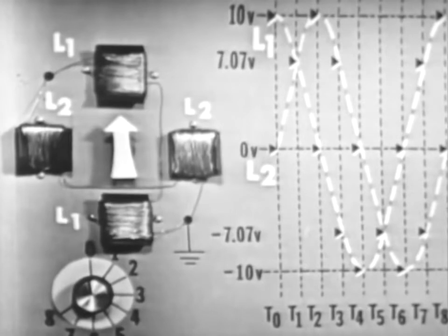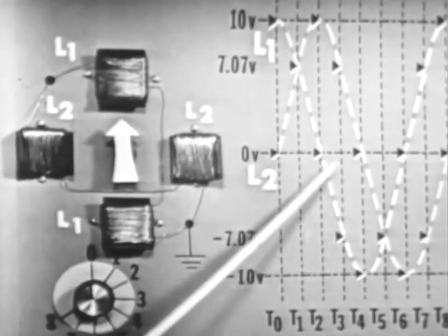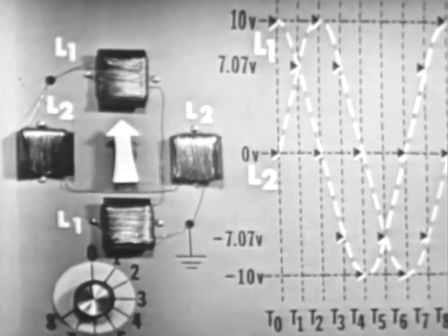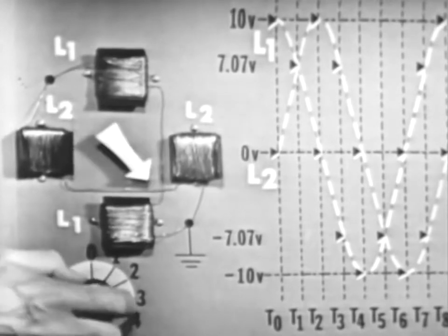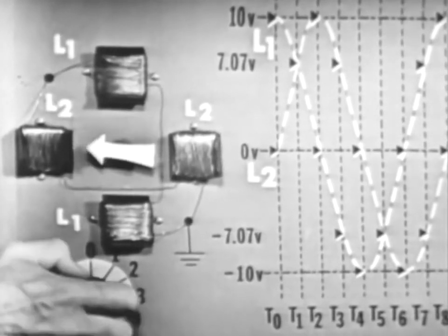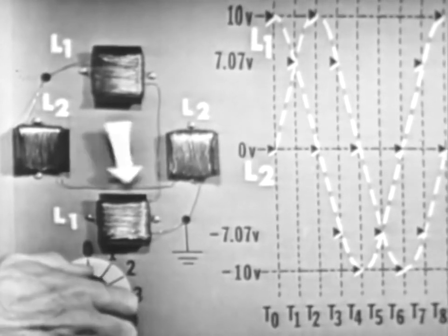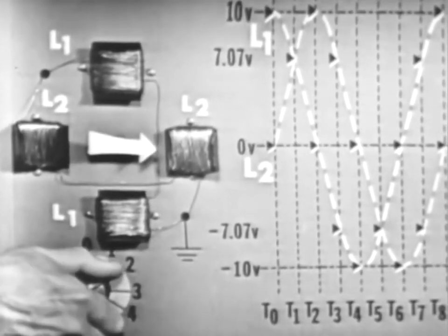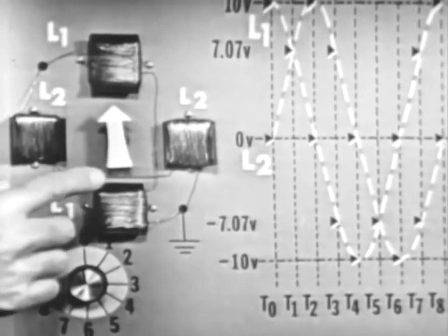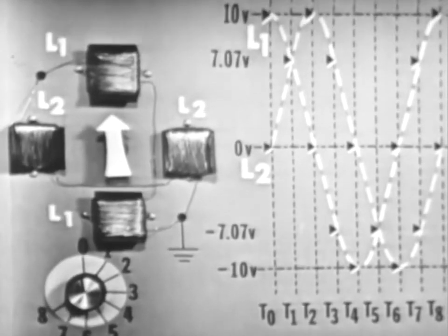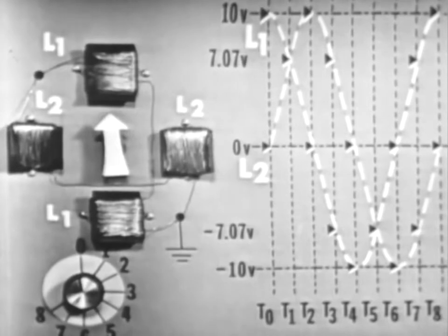Okay. A rotating magnetic field is achieved by applying out-of-phase voltages to the stator or the field windings, which we represented on this demonstrator. Now, you should point out, Bob, that the most effective phase difference to use is 90 degrees, as we did. Right. It'll work at other phase differences. In fact, any phase difference other than 0 or 180 will give you a rotating magnetic field. But as you said, the most efficient one is 90 degrees phase difference, and that's probably the one most commonly used.